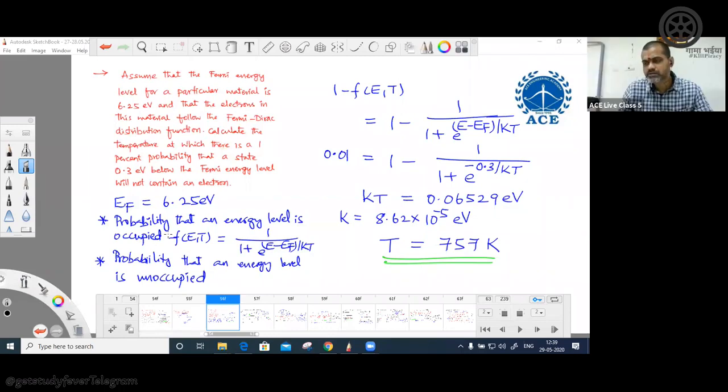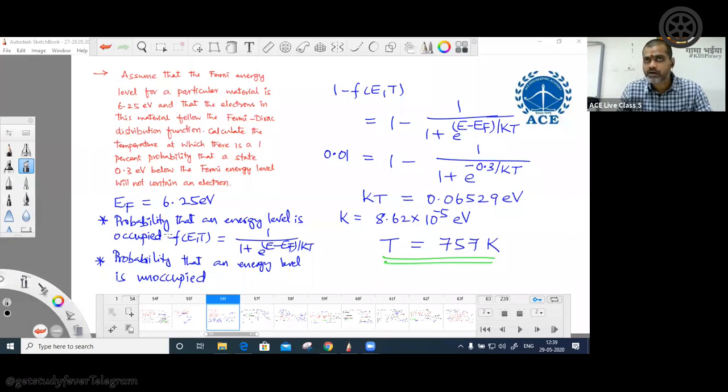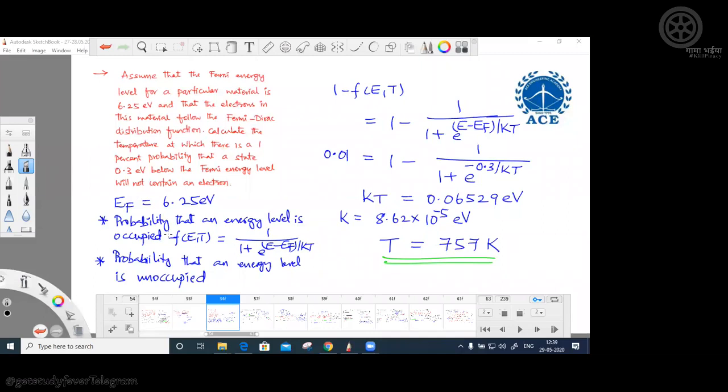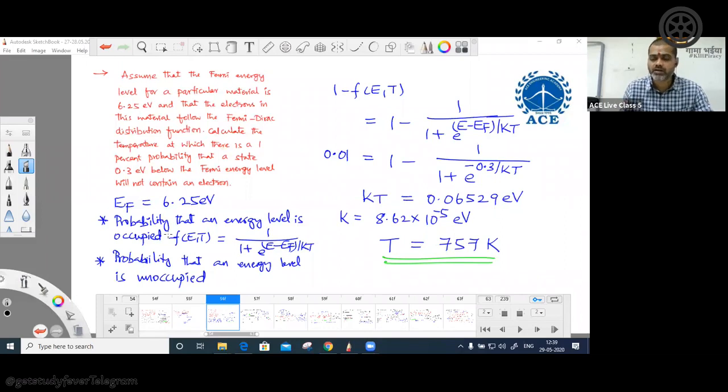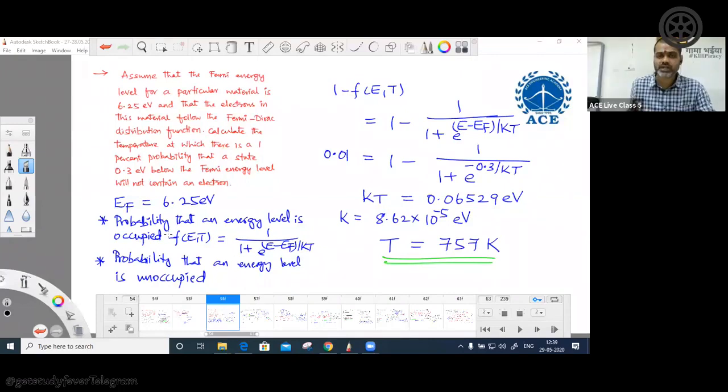Why is the conduction due to holes? How are you getting holes? What is a hole? It is a vacant space created when the electron is not occupied. When the electron creates a vacant space by leaving, where has that electron gone? To the conduction band, obviously. So you cannot see one without the other in semiconductors. The very beautiful thing with semiconductors is that if you create an electron, correspondingly there is a hole that is going to be created.